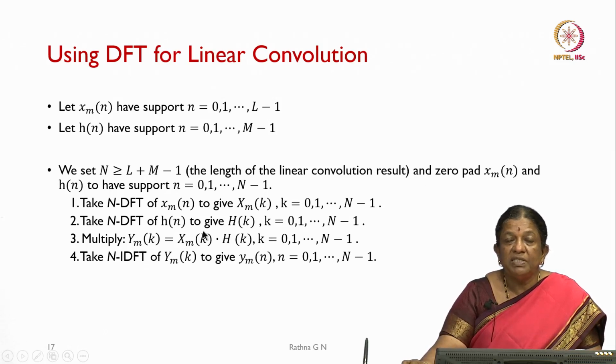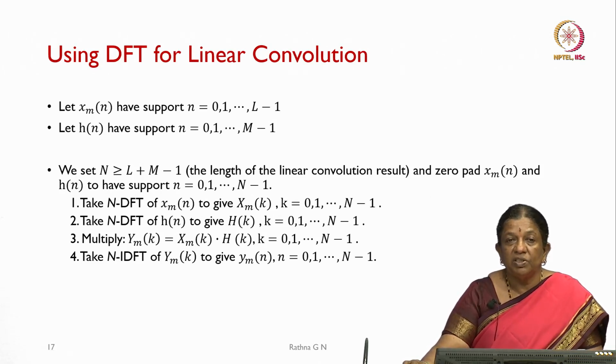Although we are doing this 3 times, since the N-point DFT of two signals and the N-point IDFT cost the same, and in between we have to do a complex multiplication, in spite of that our computation time is lower than the direct DFT, and the result is equivalent to our linear convolution.